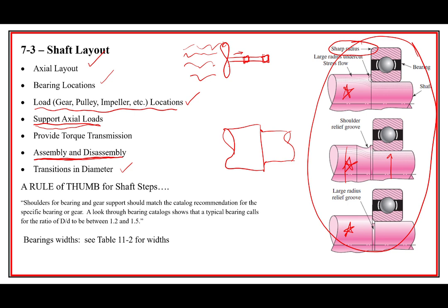If you have a helical gear running on something, as opposed to a spur gear, right? A spur gear, you could draw like this right here. It just has, when looked at, a tangential and a radial load, right? The radial load is a necessary thing because the gear teeth have an arc to them, and so a gear tooth looks like this.